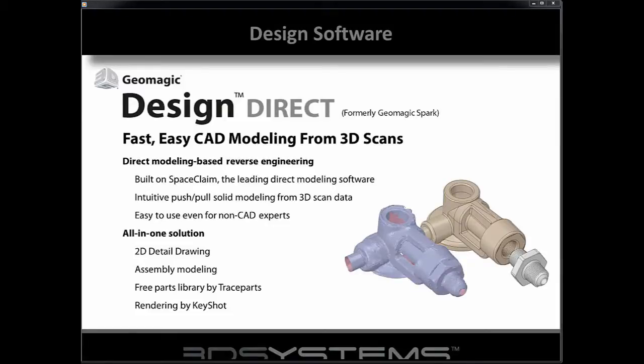And primarily, it's designed around a very robust direct modeling package from SpaceClaim. SpaceClaim is the leading direct modeling software, and direct modeling is a flavor of CAD modeling that involves a simplistic, intuitive push-pull mechanism for modeling. So if you have a face and you want to move it to change the offset, you just click it and drag it. There's no parameters to input. It's as powerful as parametric modeling. It's just a different technique. It's a different way of getting to the same result.